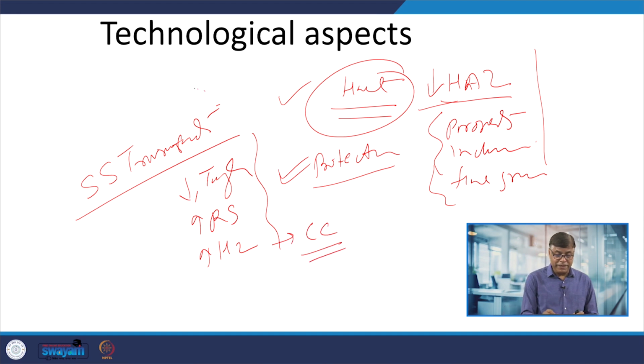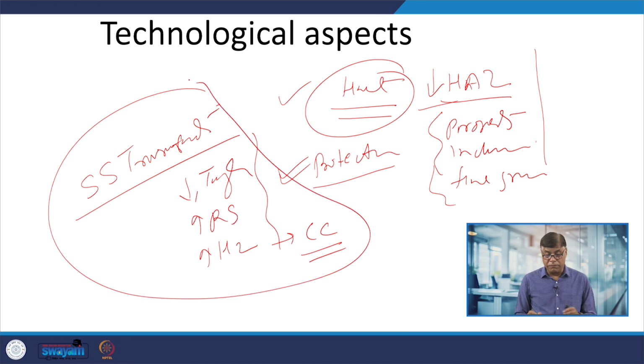So, these things need more careful attention regarding the choice of preheat, choice of filler, and post weld heat treatment in order to control their adverse effect on the weld joint and the related failure tendency.